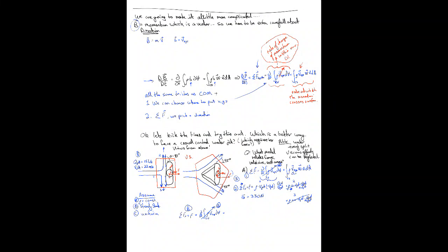So we're going to do 1, 2, and 3, going clockwise around, starting with the entrance jet as 1. And that entrance 1 is going to be the exact same as before. We have a rho, a v jet, times a negative v jet. And that first v jet is the vx, the x component of our jet entering our control volume relative to our coordinate system.